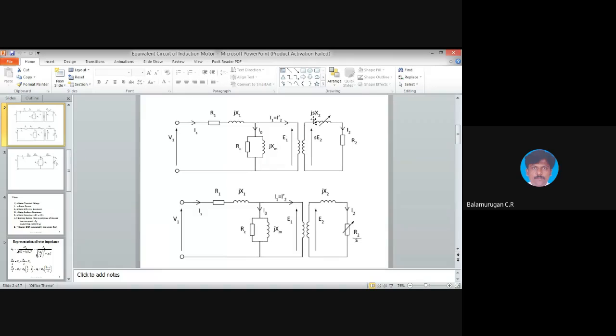So what is the need of this equivalent circuit? Do you have any idea why we have this equivalent circuit? What parameter are we finally supposed to calculate from it? What is the need for a step-by-step procedure to obtain the equivalent circuit of a transformer or induction machine? We will have two different circuits: the secondary has a separate circuit and the primary has a separate circuit. We are making the two circuits into a single circuit. That is the role of the equivalent circuit of the system. And if it is a single circuit, it is easy to find the parameters of the circuit.